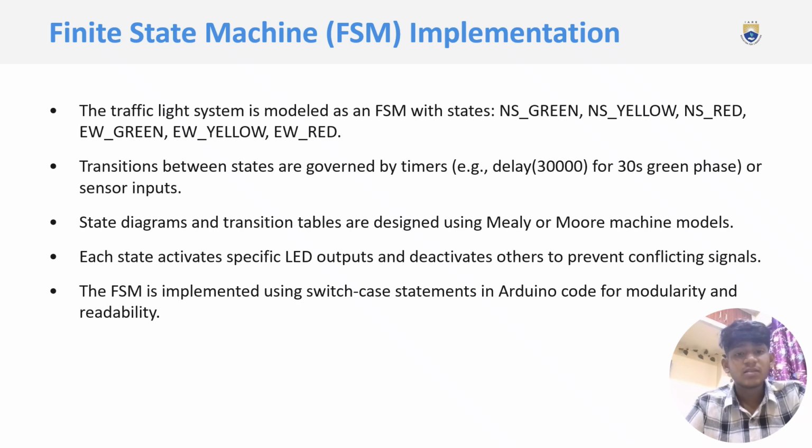State diagrams and transition tables are designed using Mealy or Moore machine models. Each state activates specific LED outputs and deactivates others to prevent conflicting signals. The FSM is implemented using switch-case statements in Arduino code for modularity and scalability.